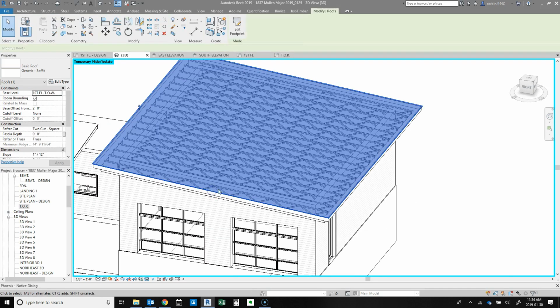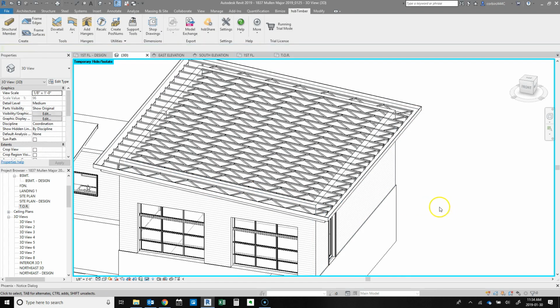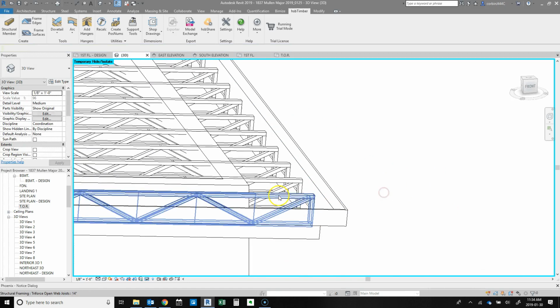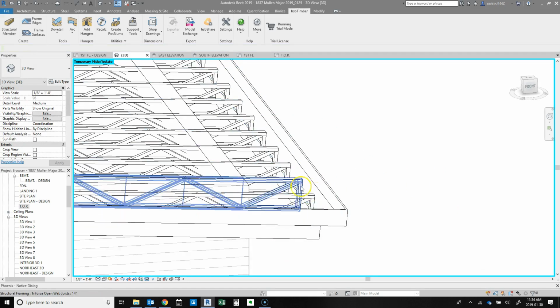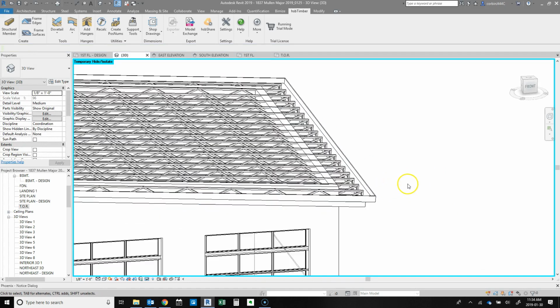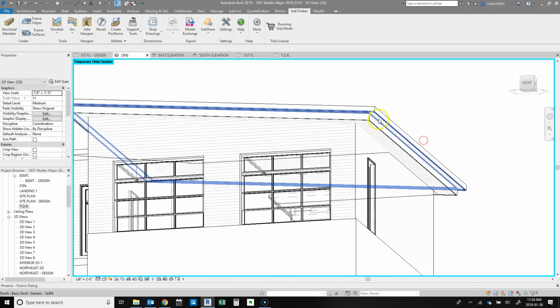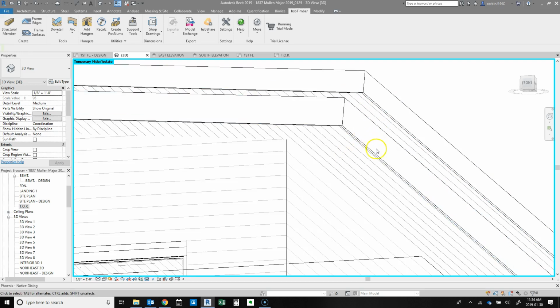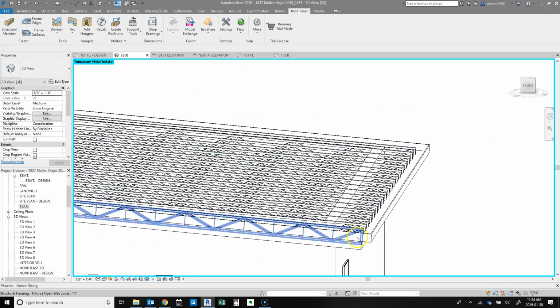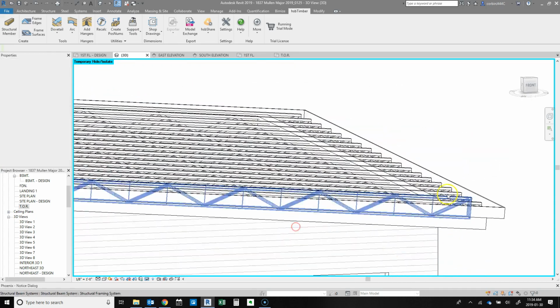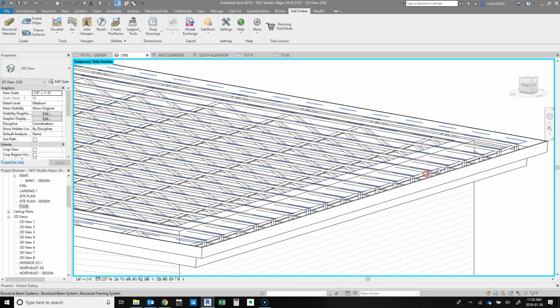Now when we open up the roof here, you can see all our joists in there. And then the contractor, when building this, would just run a 2x6 over from the top of these to create the stepped fascia portion there. And the purpose of the stepped fascia is to create venting near the top of the roof. So this bottom part of the soffit would not have any venting, but the top part would, and that would allow airflow at the top of the roof surface.